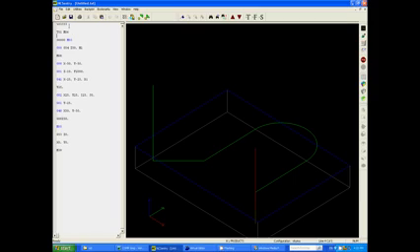Alright, so at the beginning of the program for a FANUC controller, and HAAS is similar as well, we've got a number, or a letter O, sorry, followed by a number. Now what that block of code tells the machine is the program number, and the function of that is basically just to display in a program list so you can find what you're looking for.